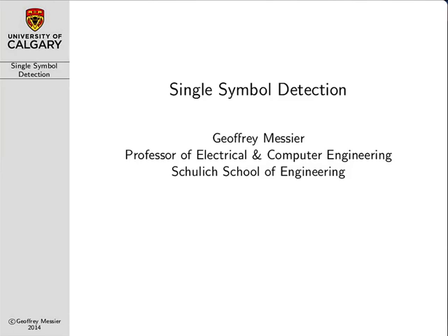It is worth noting, however, that there are some important cases where memory does exist in our information stream. Sometimes memory can be added by our channel, and sometimes we add it intentionally. So for the channel case, if we have a dispersive channel such that our transmitted signal is smeared in time, so that it overlaps with the symbol that comes after it, we get what's known as intersymbol interference, where the symbol that came before us is actually interfering with our current symbol.